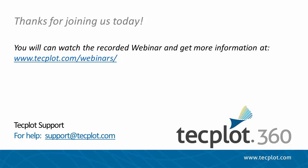Do these ASCII files still load into Tecplot slowly? Yeah, so that's a really good question. We did mention early in the webinar that ASCII is recommended for small data. Tecplot deals with binary data natively only. So whenever we load an ASCII file, Tecplot 360 goes through a process of converting ASCII to binary. So if you have a lot of data that you're going to be processing, you definitely want to prefer the binary data files. So ASCII is good for small data, but if you have a lot of small data, you may want to convert to binary.